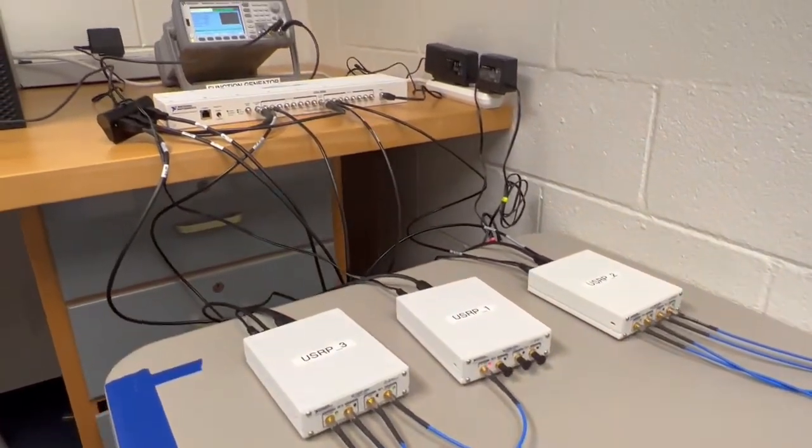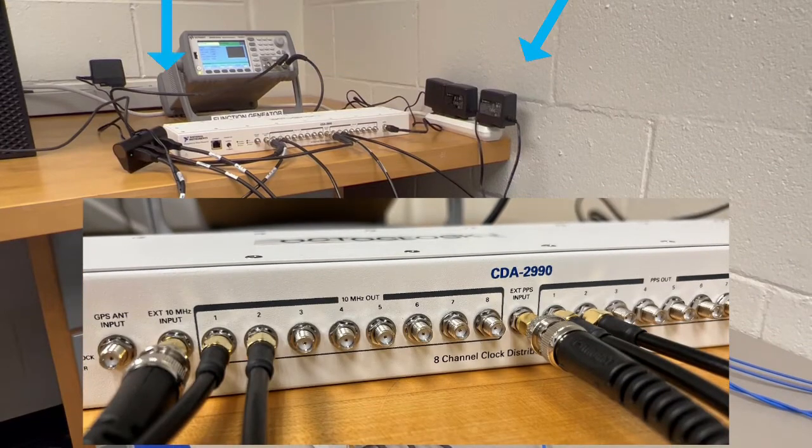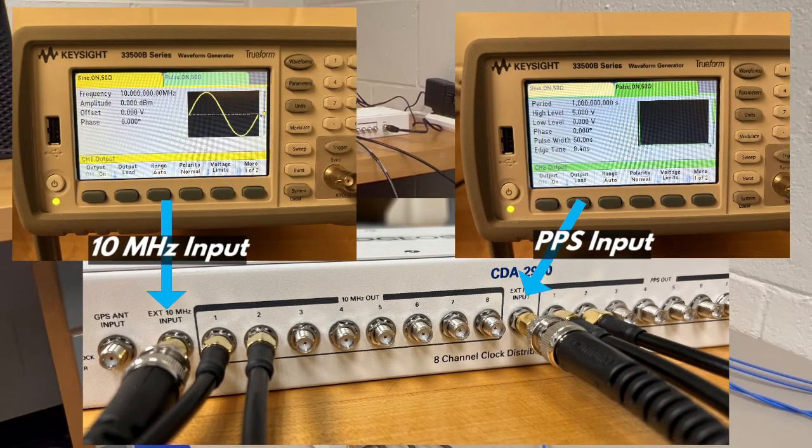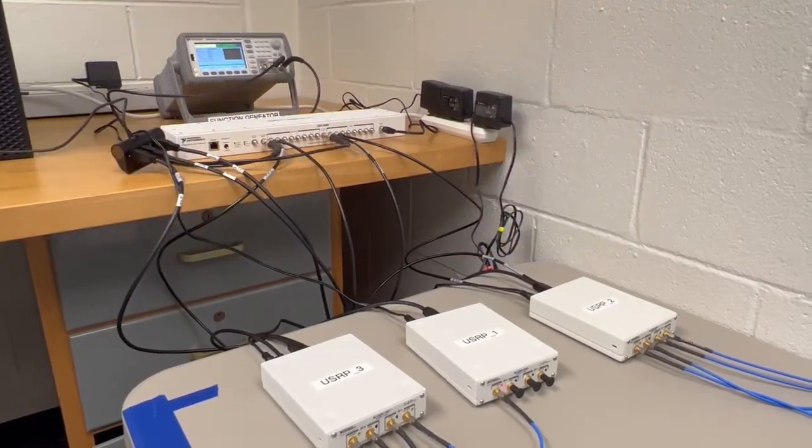Directly behind the USRPs is an octoclock and wave function generator. The octoclock performs time synchronization among the received signals, however it does not have a local oscillator internally and therefore requires a 10 MHz input and pulse per second input, which is being supplied by a wave function generator.